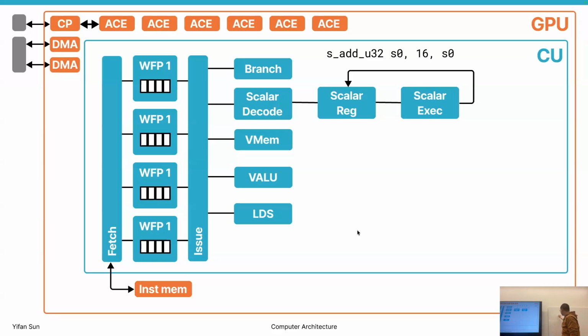So we have a multiplexer here and a multiplexer here, right? All of them are connecting to both multiplexers. Then we need control logic to select which one can go into the ALU. So here is the multiplexer, and the decode stage is roughly deciding the values on these control wires.